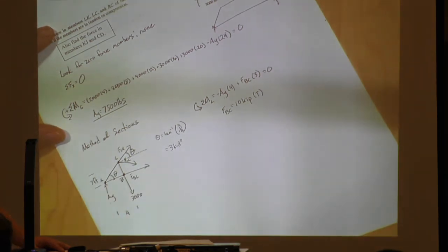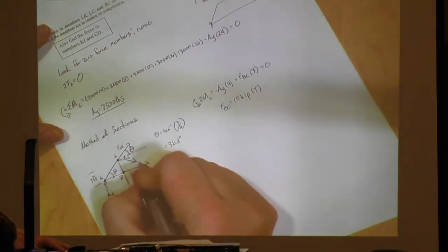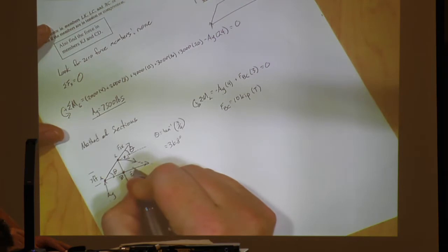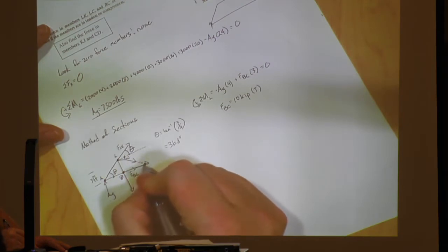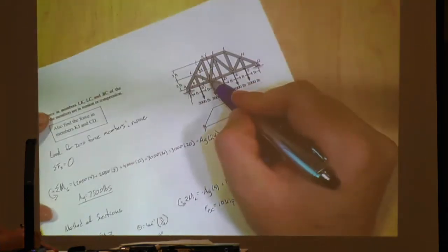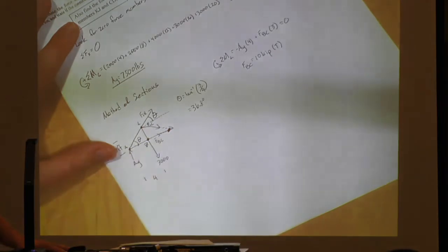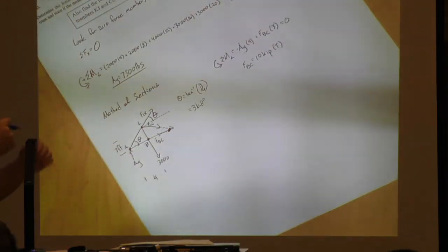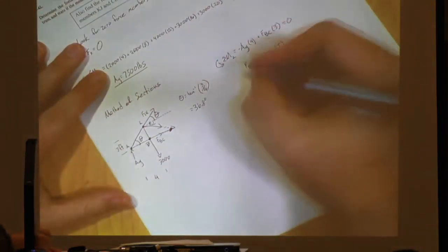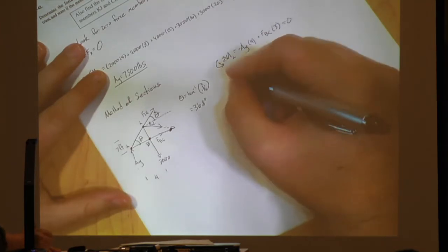Now, where do we want to go from here? What's the next good place for a moment? Okay, about C. So even though it's not there anymore, C, the vectors still point to it, and we know the geometries of where they intersect. So we can have distances to make a moment from. So we take our moment about C, we're just going to kind of be imaginary in here because we're dotting it out, and we're saying that's where the vectors intersect. Does that make sense to everybody? Right.